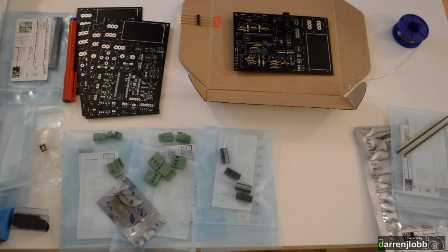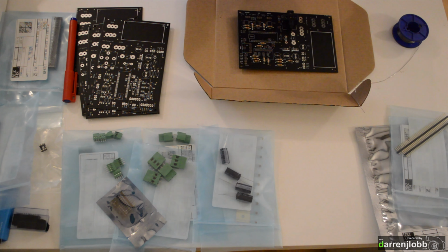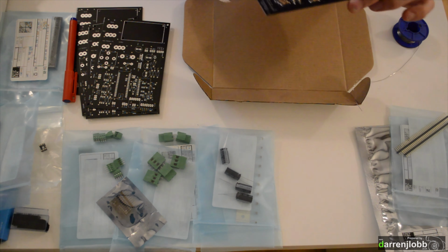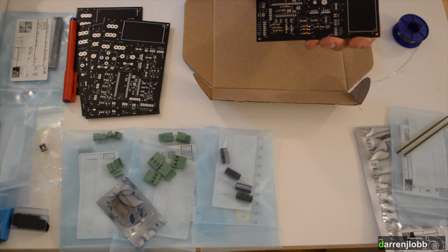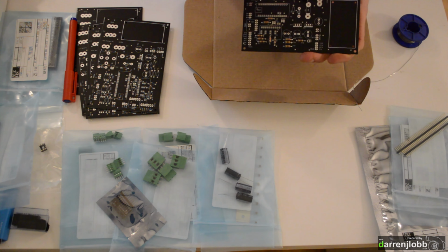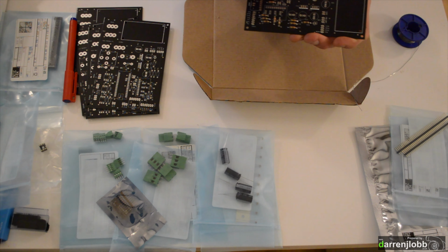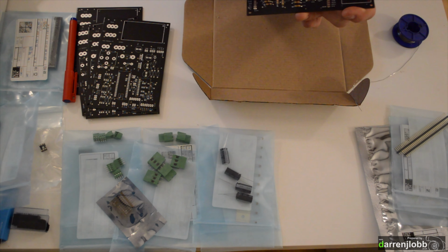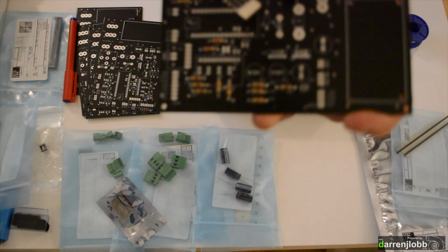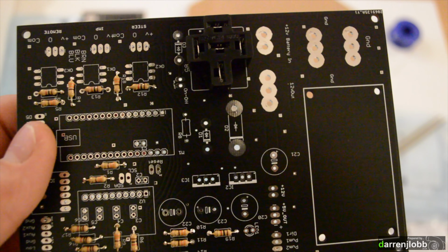Right, that's all the resistors done now. So moving on to the diodes. We've got two different sized diodes. We've got these 1 amp ones and the slightly smaller ones. We'll do the smaller ones first. The only thing that's different with diodes to resistors is it does matter which way around they go. The function of a diode is to only let current pass in one direction, so they need to go the right way. You can see the diodes have got a little white strip on them, and the PCB is also marked up with a white strip at one end, so just line the two up, and otherwise it's exactly the same as the resistors.